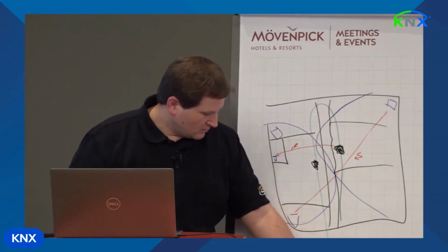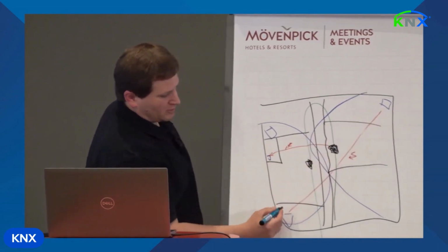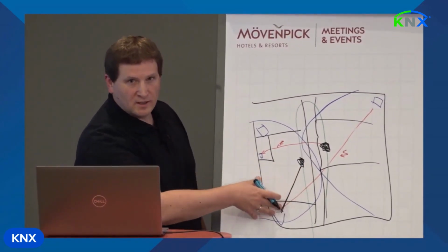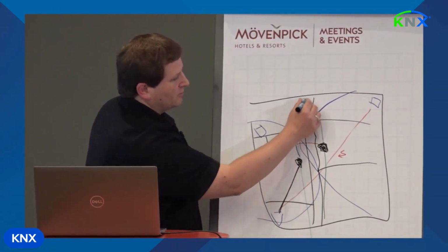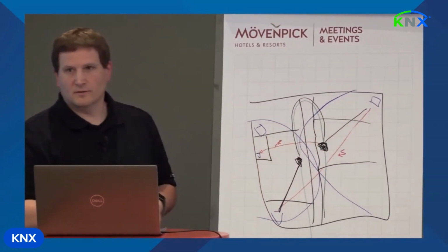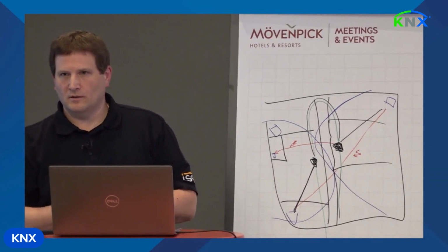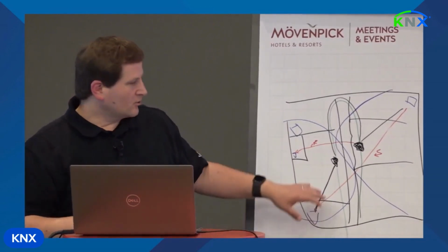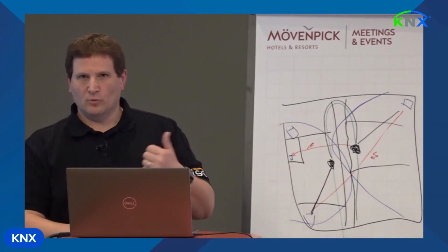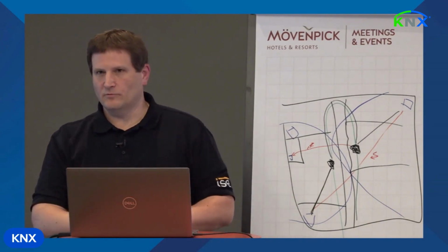In the case that I've just drawn here, if this communication would be broken, it would be possible to communicate between this device and this media coupler in domain A. Then the frame would travel on the green cable to that other media coupler and would be sent out in domain B to this device. And the analogy to Wi-Fi I also mentioned earlier: there it's also better to have an Ethernet backbone and multiple access points instead of having only one access point and repeaters. You always get better signal quality, better experience overall, less telegram loss.